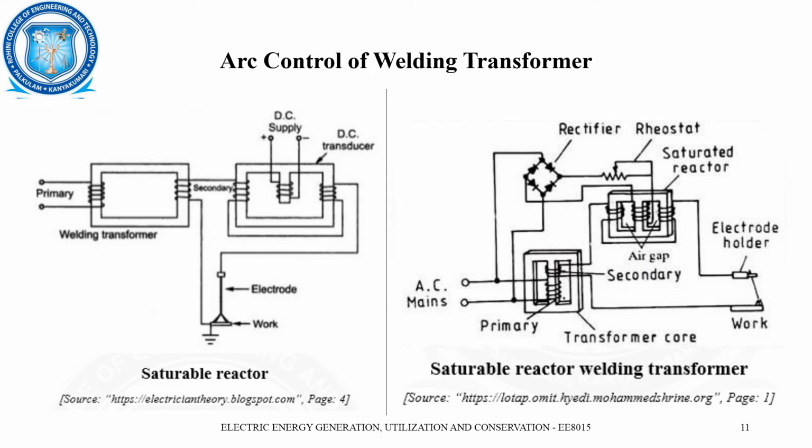Here, the higher the DC current, the more the reactor approaches saturation. This changes the reactance of the reactor. By changing the reactance level, the current can also be changed appropriately. By using the above reactors, current can be controlled, and this helps in the formation of the arc for the welding purpose.